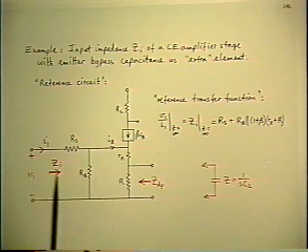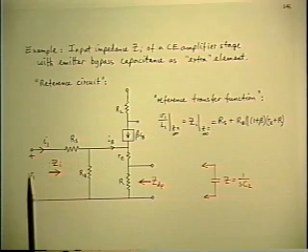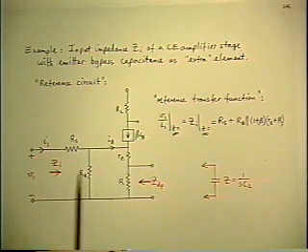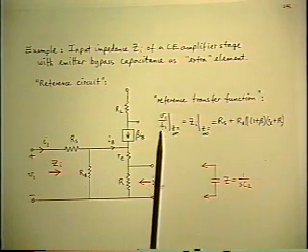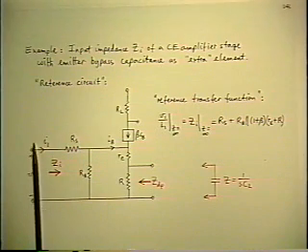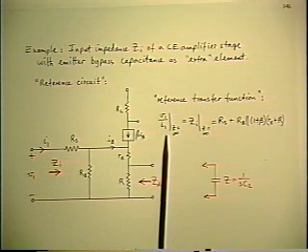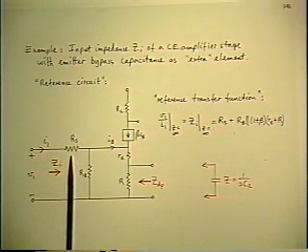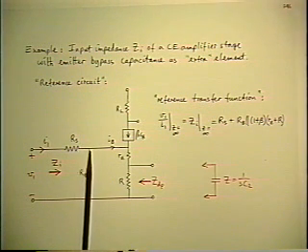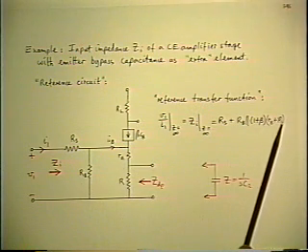Okay, let's calculate the input impedance of the common emitter amplifier, and suppose that we've started by calculating the input resistance of this model that doesn't have any reactances in it. So the input impedance is V1 over I1, where V1 is the voltage of the input, I1 is the current of the input. Obviously, by inspection, the input resistance is RS plus RB in parallel with the reflected RE plus R.